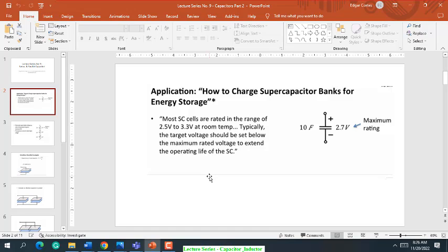There are instances that it will blow up or bloat, the capacitors swell. By the way, class, when you do some circuit experiments at home or at work in the future, there's a technique on how to discharge a capacitor. You just short its two terminals using a resistor or load bank, or you short it to ground. Then it will discharge, because we know a capacitor is also an energy storage. So remember this.